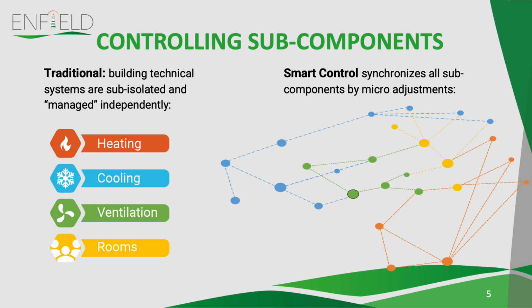But what is the problem with a classical control system? In fact, it's not a novel technique. It exists from the last century, and each device has its own controller. Usually these controllers are even built into devices. But the main problem is that each device is controlled separately. Heating is making its own decision, cooling is making its own decision, etc. And they do not talk to each other. And also they have quite limited information.